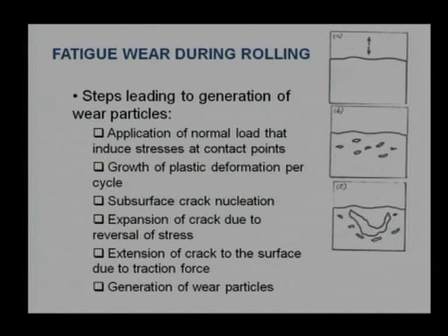If a number of voids come closer to each other, they will make a bigger void, a larger void, and if it is loaded and unloaded continuously, this void will extend up to the surface and a whole chunk will come out, which will generate a pit on the surface. So rolling as well as sliding are generating pits, but with different kinds of mechanisms. Here the lateral direction force matters a lot.